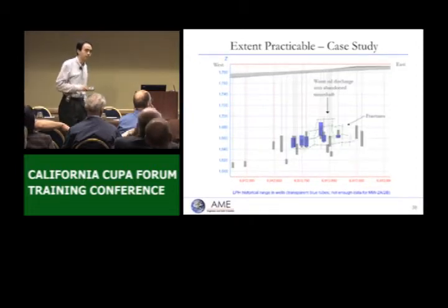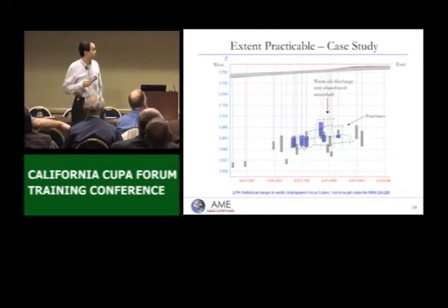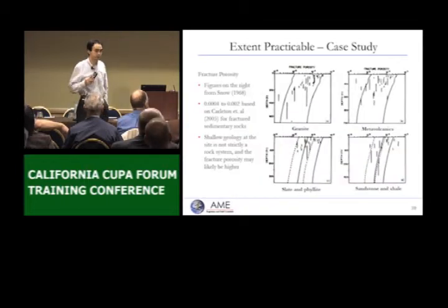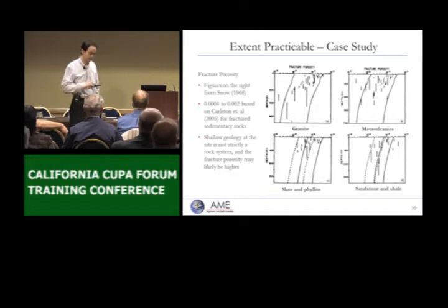The distribution and mobility of product in the subsurface depend on site-specific information: soil properties, product types, thickness, and hydrogeologic conditions. Then the recoverability should be evaluated on a site-by-site basis. So according to that principle, the goal to remove LNAPL to the maximum extent practicable also needs to move toward site-specific goals corresponding to the current state of knowledge. Some progress has been made, which is a good thing, but a lot remains to be done. And that concludes my talk. Thank you.